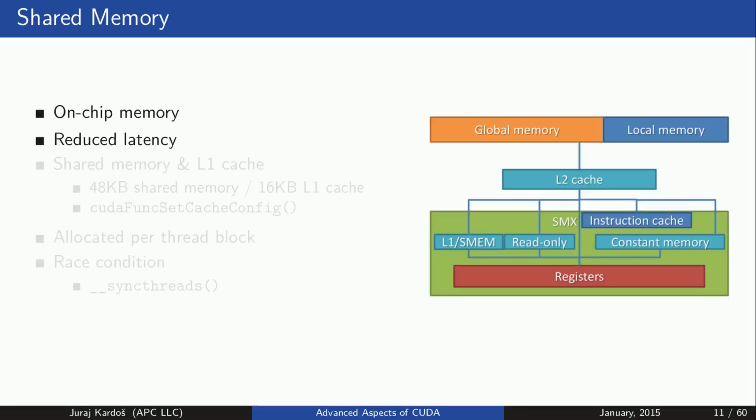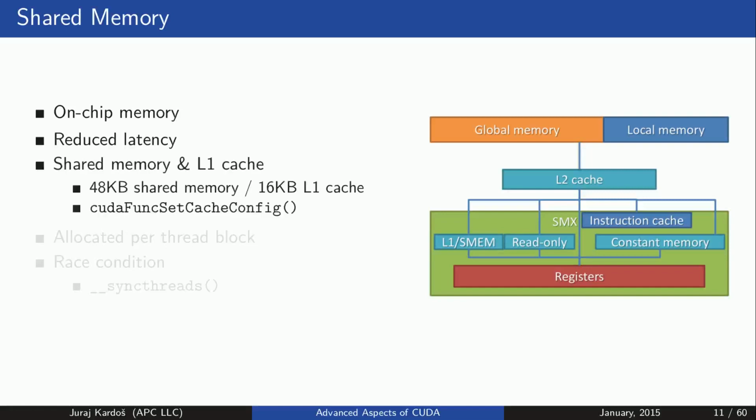Because it is on-chip, shared memory is much faster than local and global memory. In fact, shared memory latency is roughly 100 times lower than uncached global memory latency, provided that there are no bank conflicts between the threads, which we will examine later in this section.